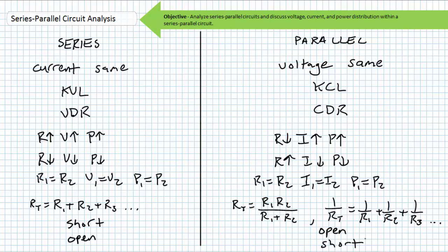Visualize circuits from the perspective of flowing current, and think about voltage at the nodal level. If current has no choice but to flow through a single path, elements in that path are in series with one another. If current has a choice between paths, those paths are in parallel with one another. If two paths are hooked to the same two nodes, these paths must necessarily have the same voltage across them.